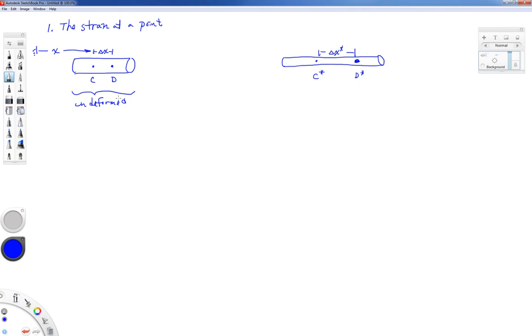Soon we're going to shrink that delta X down to 0 to get the strain at a point, but we're going to start out with a little bit of separation for right now. Of course, in the bar, we could have a little bit different strain distribution from one side to the other. What I'm going to do is I'm going to take this bar and I'm going to stretch it out, and I can pick it up and I can move it over at the same time. So I'm just going to draw a little arrow here, and I'm going to write down, I'm going to stretch and move the bar.